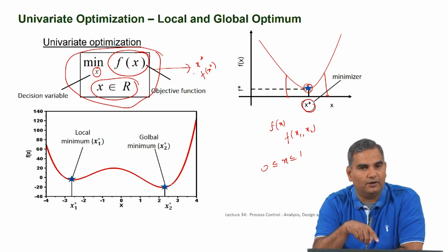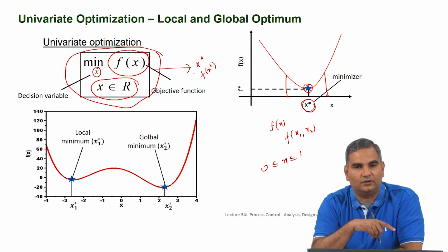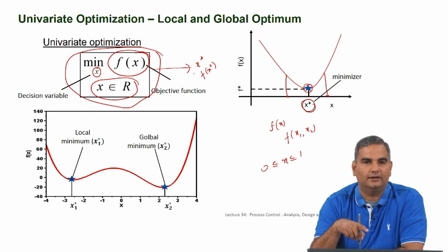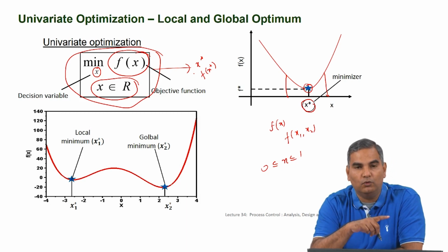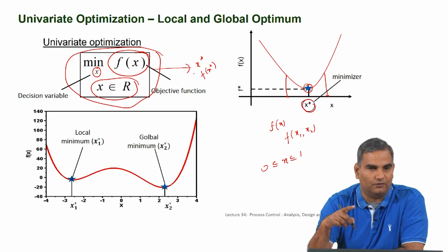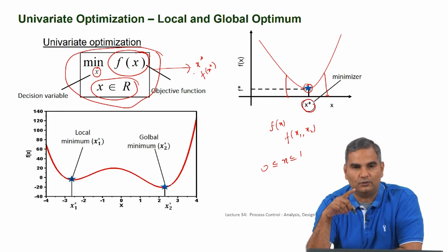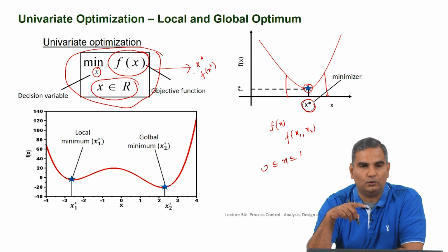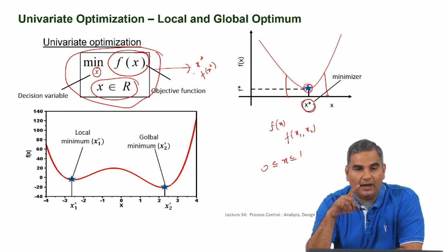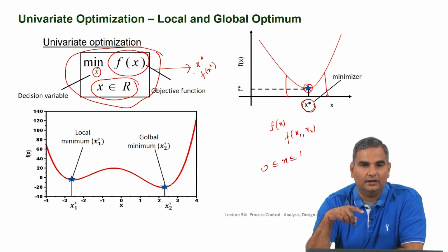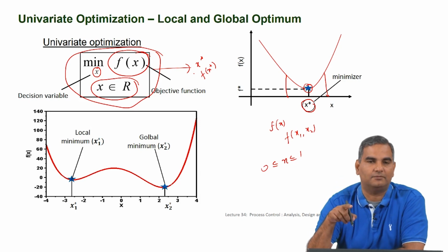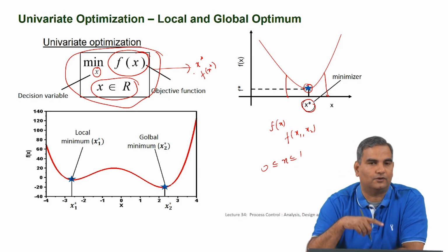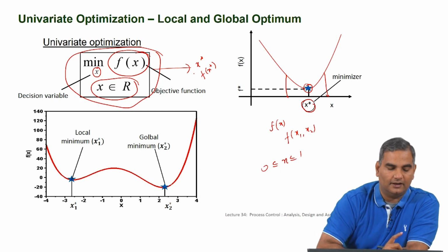So, this is very important to remember, because when I connect this to control, we are going to write the optimization problem with decision variables which are the move plans, the choice for the input values that we talked about. So, I have uk plus 1 all the way up to uk plus m minus 1. Those m variables, if I can find values for them such that some objective is optimized, then I have my move plan. That is the connection between control, model predictive control and optimization. This is something that you should keep in mind.